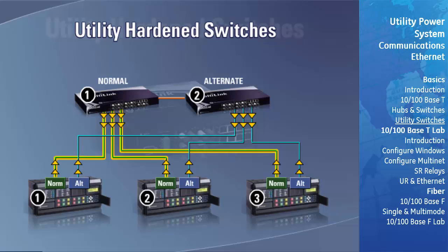There will normally be no other communication on the alternate ports other than the link pulse traffic. If there is a failure of the fiber connecting Universal Relay 1 to the normal switch, Universal Relay 1 will no longer receive link pulses. The loss of reception of link pulses will cause Universal Relay 1 to transmit and receive through the alternate communications